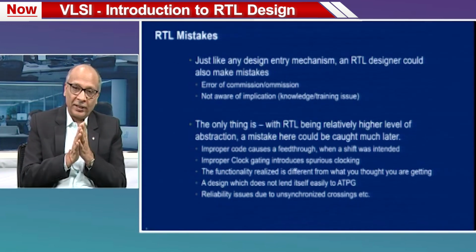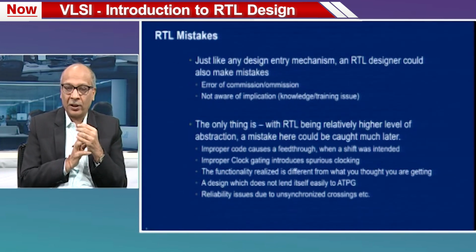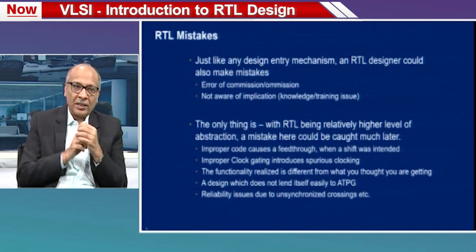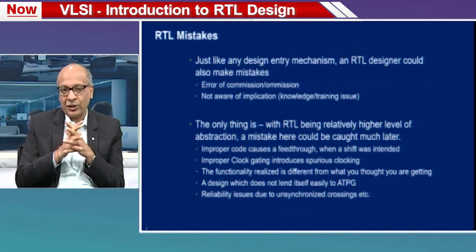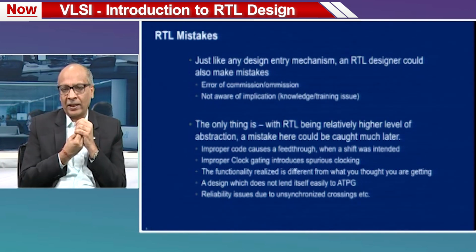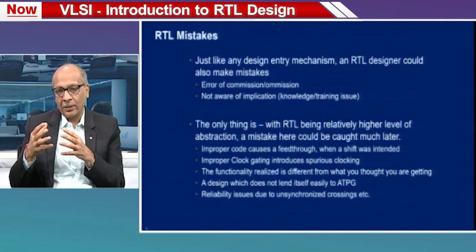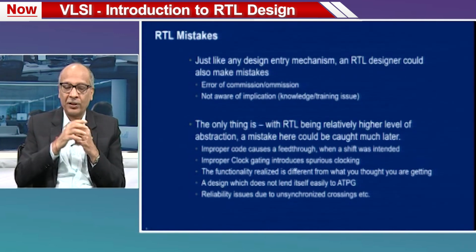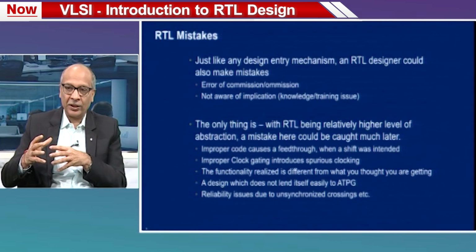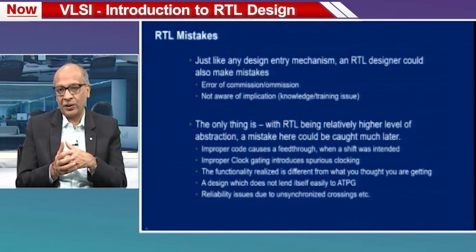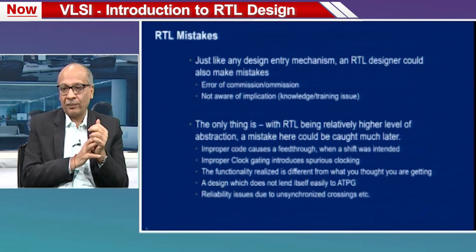Or the functionality that you wanted to realize is different from what you actually ended up realizing because of your RTL mistakes. There is something called ATPG. ATPG stands for Automatic Test Pattern Generation. We will get a little feel of that slightly later. But if your design does not lend itself to ATPG, then the testing of the devices is not very easy. So, you want to create your design in a manner so that the testing is easy, which means the test pattern generation is easy.